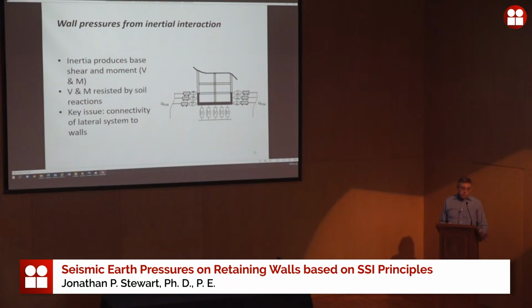If this foundation's on a rigid base, then the foundation doesn't react. That force immediately goes into the rigid ground. But of course the ground isn't rigid, right? And so that force must be accommodated through deflection of soil springs, or more realistically, the soil as a whole. But in this idealization, the soil springs. Rotation will accommodate the moment. So this foundation in reality is displacing relative to the free field, and it's rotating because of the base shear and the moment that's created by inertia.